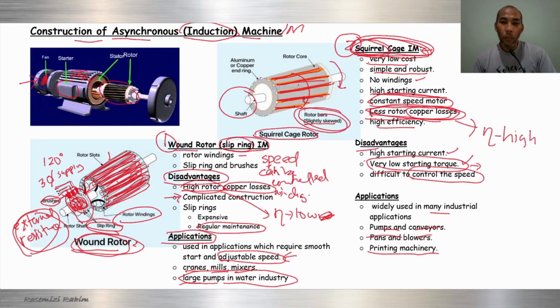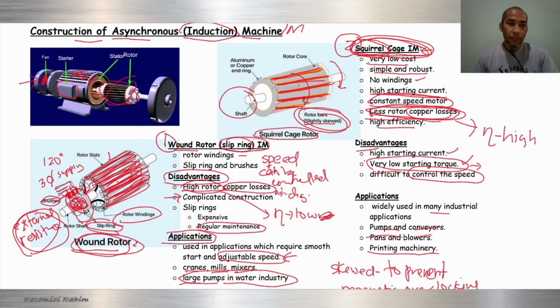Okay, why slightly skewed? This slight skew is to prevent magnetic locking between the rotor and the stator. The stator has winding, stator winding here.